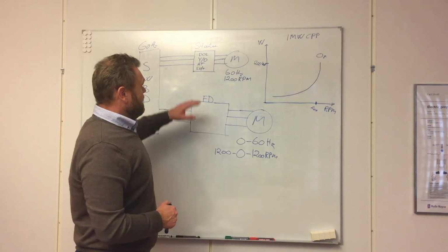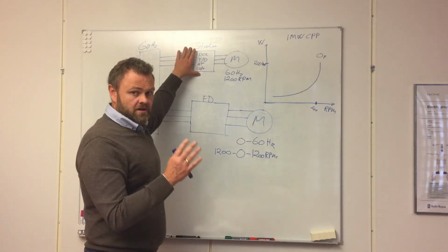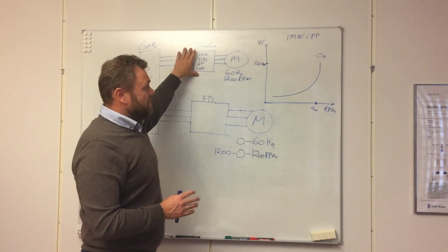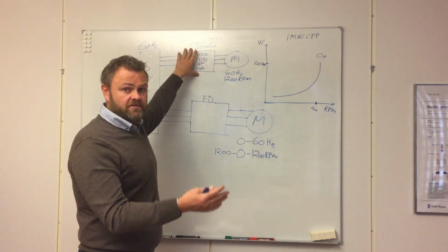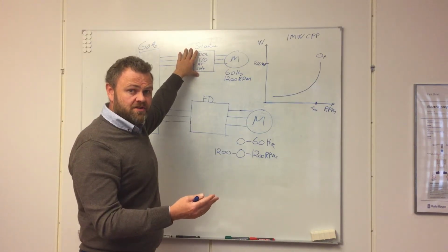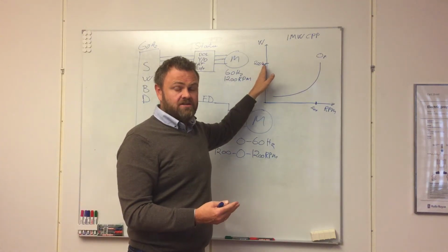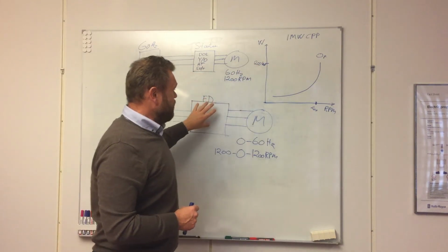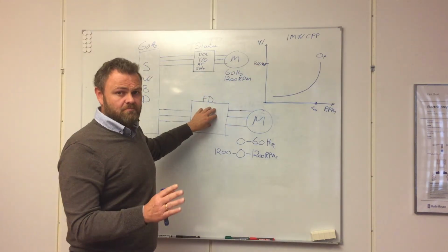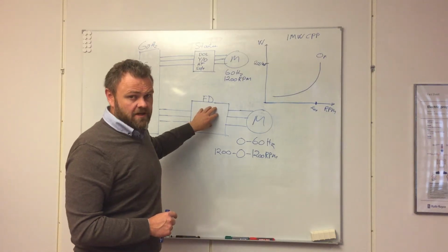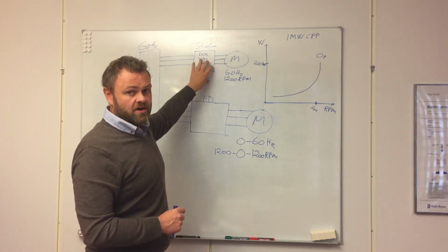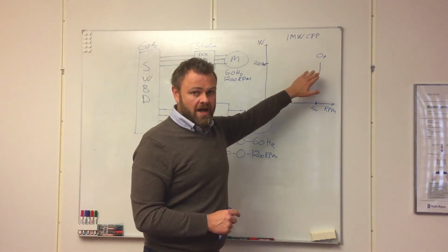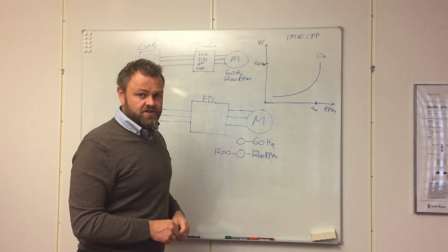So if your ship owner would like to have a starter, however, his operation of the vessel will be many hours with the tunnel thruster in duty, then you should be aware of, okay, let's have a look at this. Maybe we should add a frequency drive instead of a starter, because adding a frequency drive will take away your propeller losses.